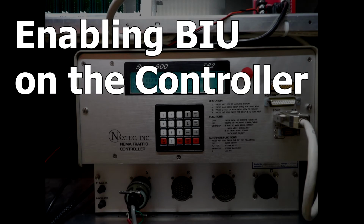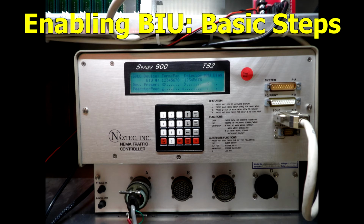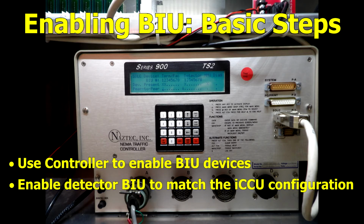Enabling BIU on the controller. Traffic controllers vary from model to model. Therefore, Polara is unable to provide support for configuring the traffic controller. But the basic steps are as follows. Use the traffic controller to enable BIU devices. Enable detector BIU number 2 to match the iCCU configuration that was selected in the previous step.